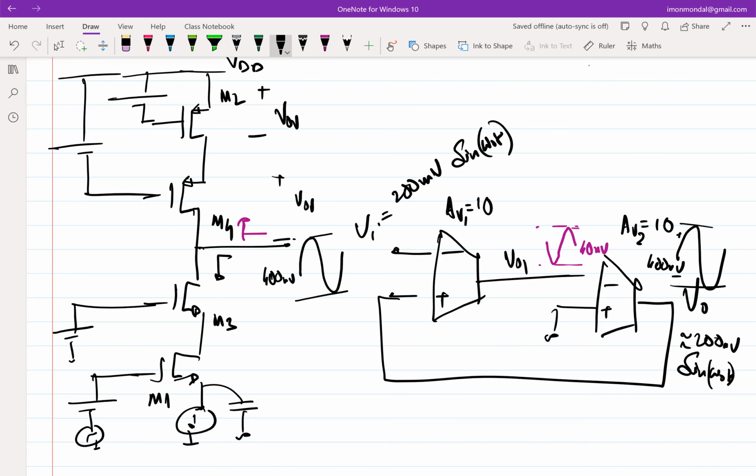In this structure, can we put the V0 terminal at the M1 drain also, for the swing advantage? That's a good question. If I put V0 here, I agree that for the lower part of the swing you are very close to the minima. But what is the output impedance looking into this terminal?